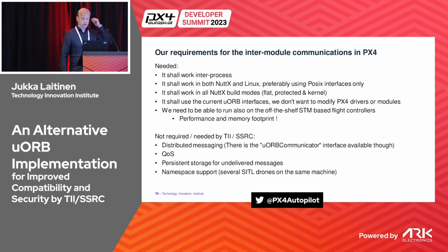It's jumping ahead of this presentation maybe, but what it means is that we don't need to run several PX4 instances on the same PC or same machine. That's because we are always running PX4 in Linux inside a Docker container. So we are always Dockerizing the PX4 and then putting the Docker into the cloud or on some PC or somewhere else.